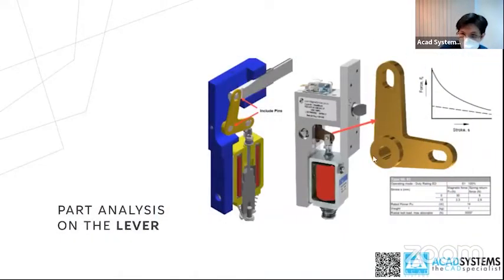So this is the 3D model that we will be carrying out our FEA simulation on. This is the lever in this machine, and this is the cross section of the machine. What you can see from here is there's a loading on the shorter end. There's a loading on this side, which is a weight, where this weight will pull this lever downwards in this direction. And on these two parts, it is the fixture, where these two parts are prevented from translating or have a rotational constraint.